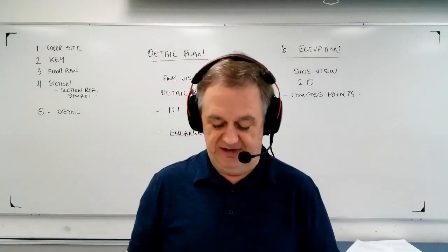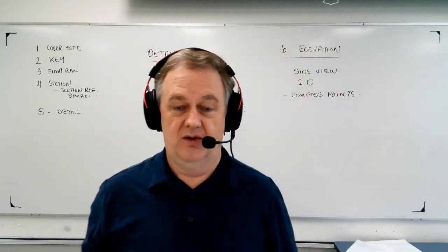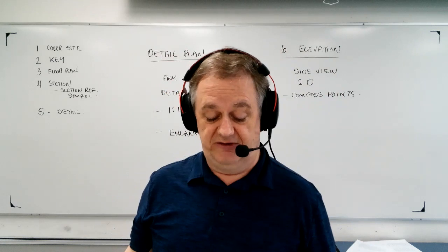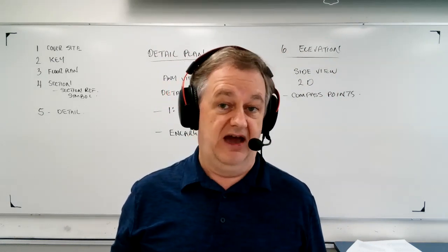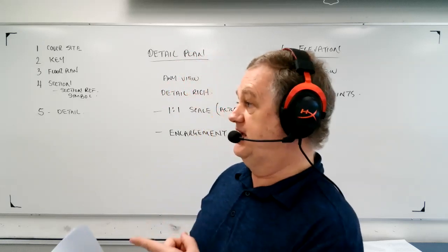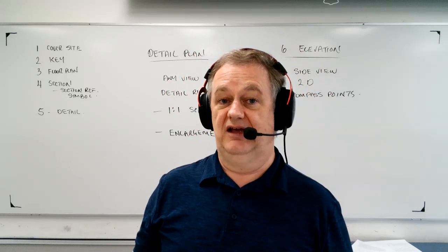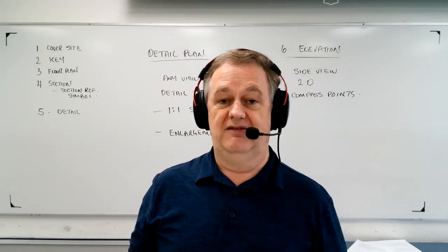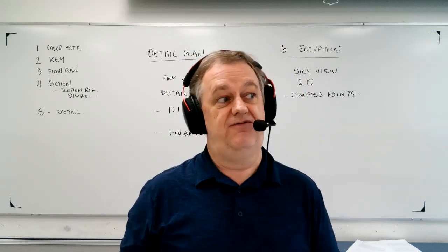Now, look at the elevation, and this is quite interesting. Which side is west on the site plan? Well, if you were on the west side of the house and you were looking east, you would be looking at what we call the west elevation. So in other words, the elevation name matches the side that faces that direction.